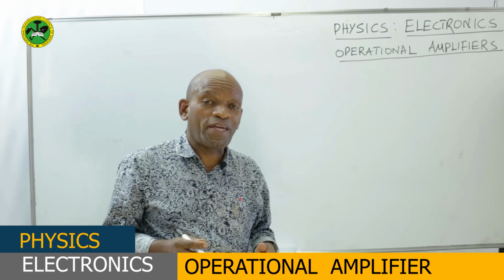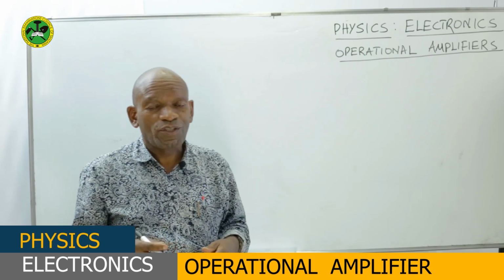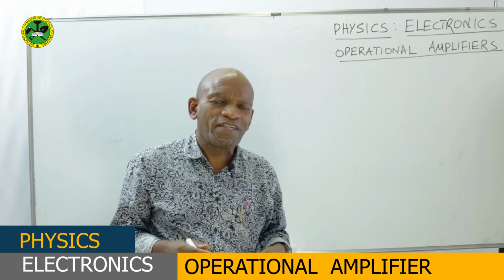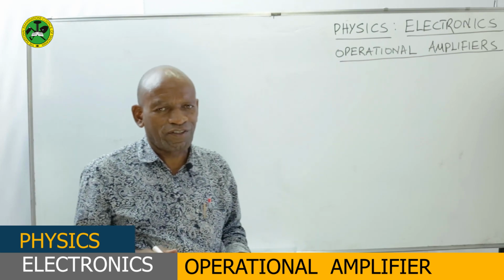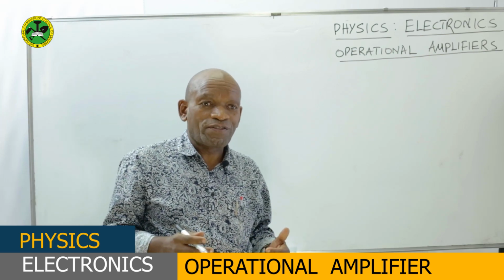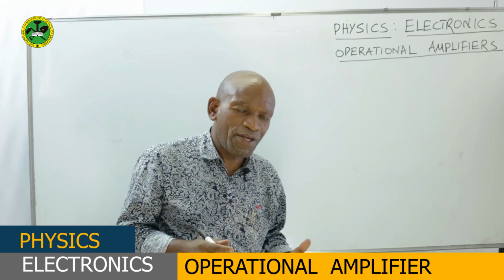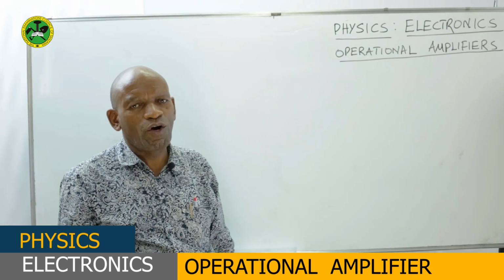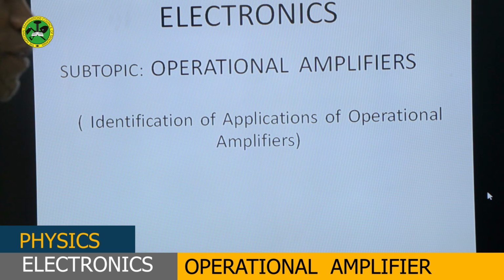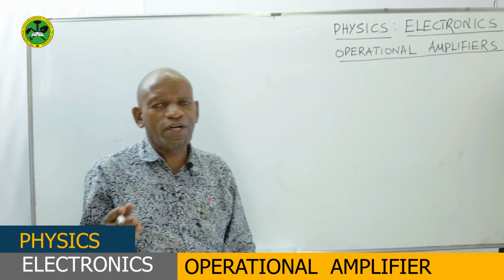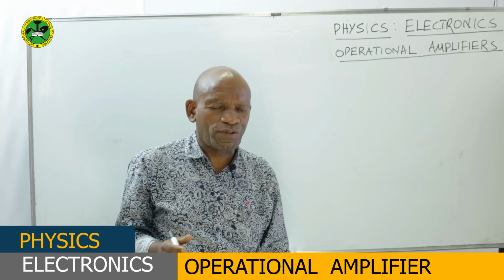An operational amplifier is an electrical device basically designed for the amplification of AC and DC voltages. An operational amplifier device has a very high input impedance of about 2 mega ohm, with a low output resistance or impedance of an order of about 200 ohms.